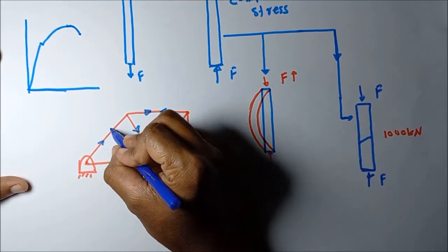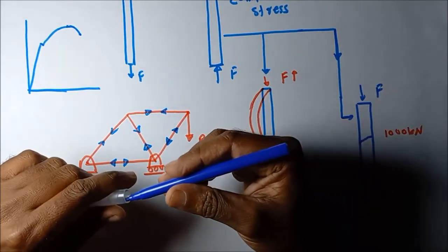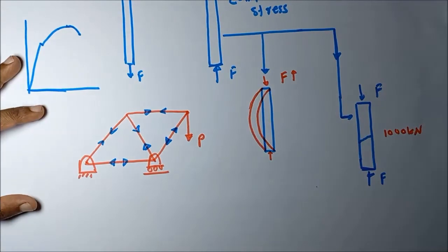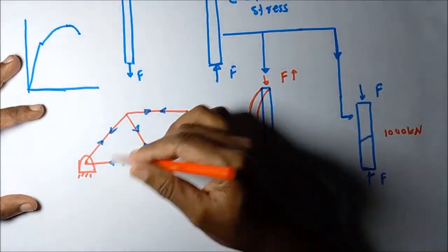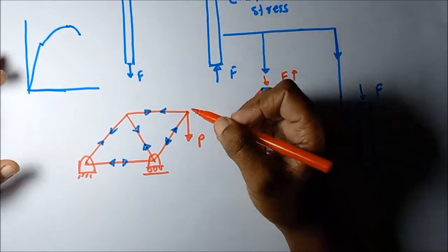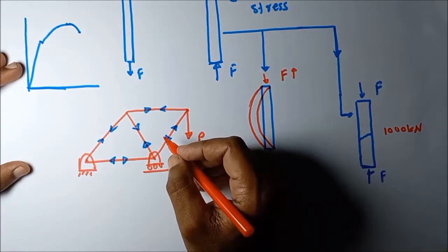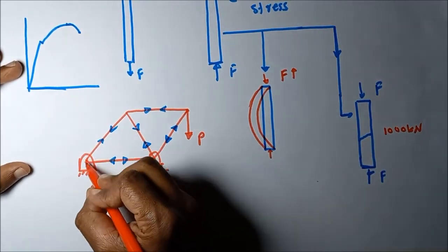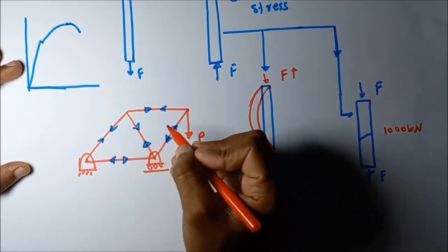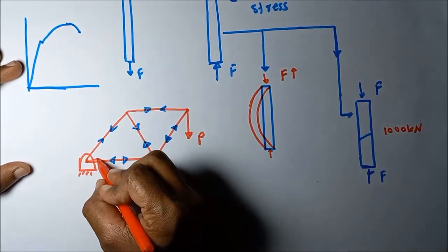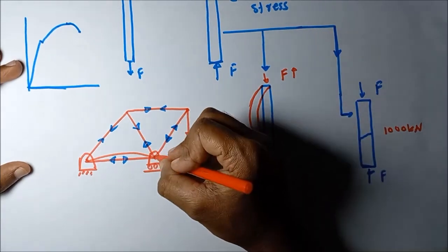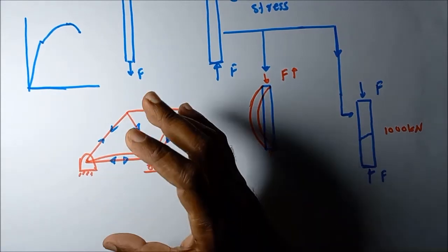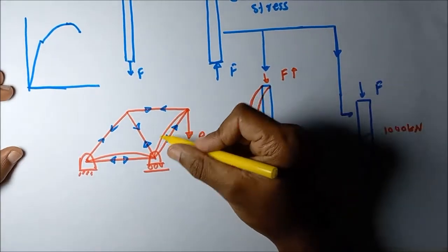Then this is subjected to tensile. Then there's a possibility for the compressive bar element, that means the bar which is acted on by compressive stresses, to buckle. There's a possibility of a buckling failure. So that means when it reaches a critical limit, it will buckle, forming this kind of curvature. Then this entire structure collapses suddenly due to the buckling of one of the elements.